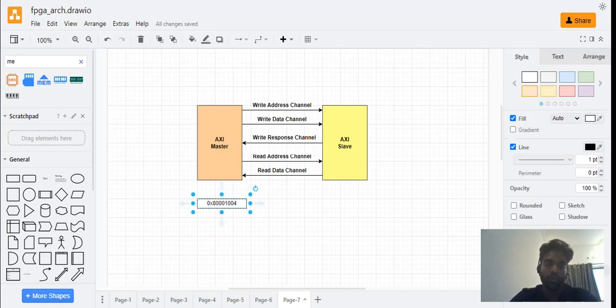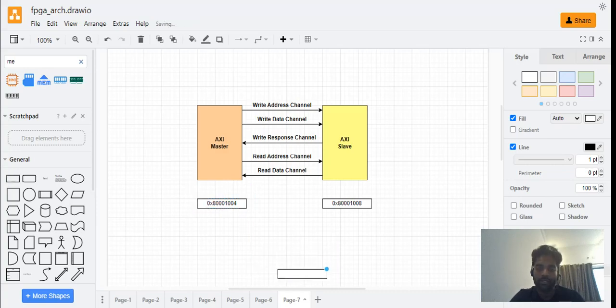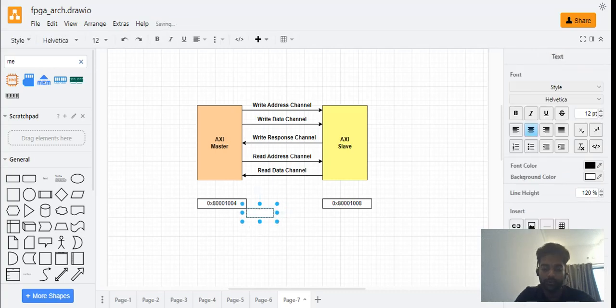So I want to send 4 bursts of data. In that case, my next address issued should be here with 8, which means I issue this address location 4567. So the incremental fashion will happen in each address location. I will be writing the burst of data. It depends on the burst size. It could be 8 bits of data, right? So each address will have the burst of data here. I can have burst 1, burst 2 like this. The size and the length depend on the parameters you set.